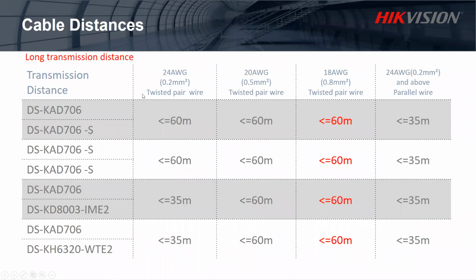All right. For the cabling distance, if you went to the site, please bear in mind to check the cable. How good is it? Is it a poor cable, or what's the type of the cable? Is it 0.2 mm square, or twisted pair or parallel? Depending on what your cable is, you're gonna find out what exactly is the maximum run of the cable you can go through.